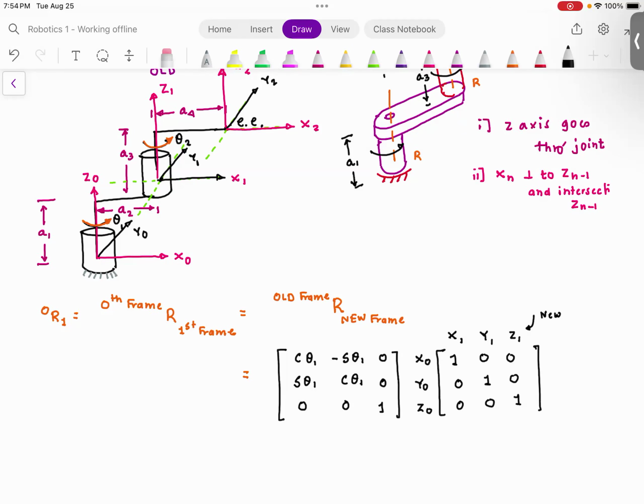The problem is not wrong if you change the x1 going towards left rather than going towards right. That would still give you the answer. But then your projection matrix is going to have negative signs popping up, and we will solve those problems. But right now, the argument here is the frame x1, y1, z1 is aligned with the frame x0, y0, z0.